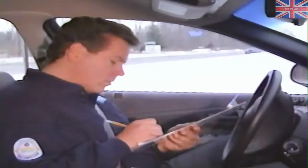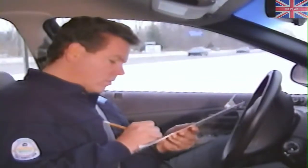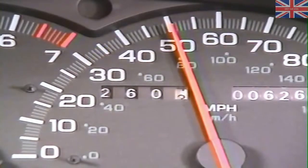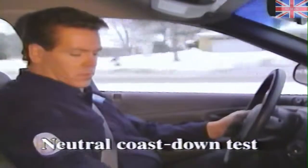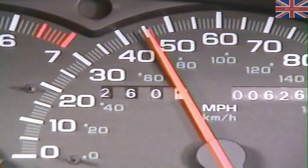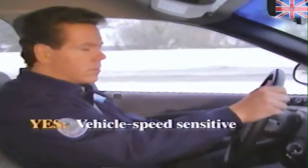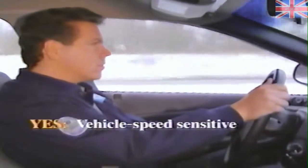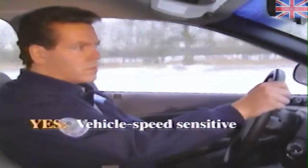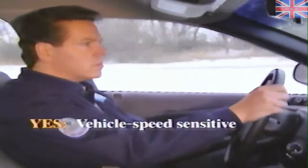Once you have noted engine speed, vehicle speed, and the frequency of the noise or vibration, accelerate to a speed slightly higher than the speed at which the problem occurs. Shift the vehicle into neutral and coast down through the vibration range and note if the noise or vibration is present. If the noise or vibration still occurs in neutral, it is definitely vehicle speed sensitive. And at this point, the engine and torque converter can be eliminated as potential NVH causes.